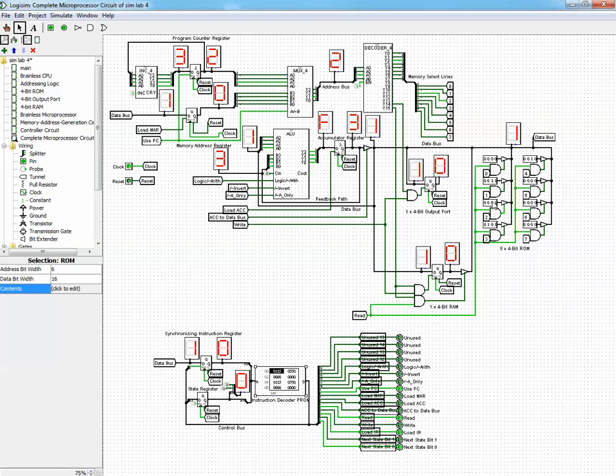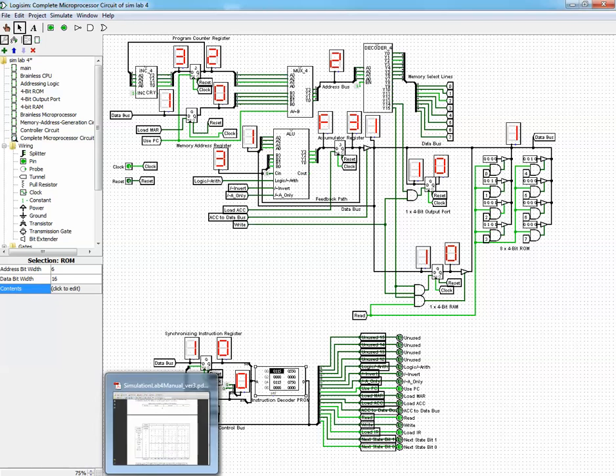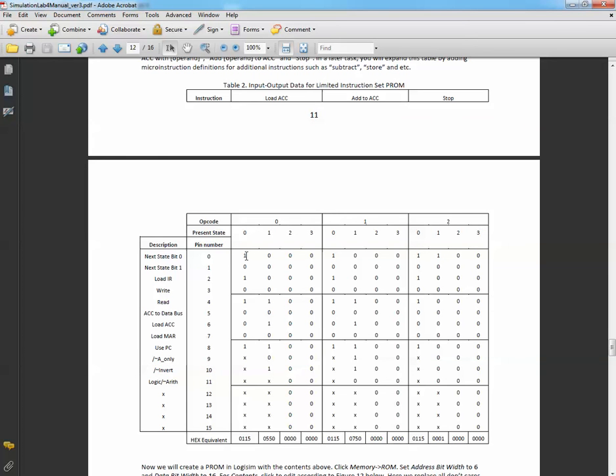1 for the address, and 1 for the data, which is 5. 1 for the address, and 1 for the data, but here we do not have any data since we have halted. Again, here it is an address. Okay, so load IR, we are loading the instruction register. We want to load the instruction register with some address in this clock cycle. And in the second clock cycle we want to do something with the data that is stored, which is loading the ACC.